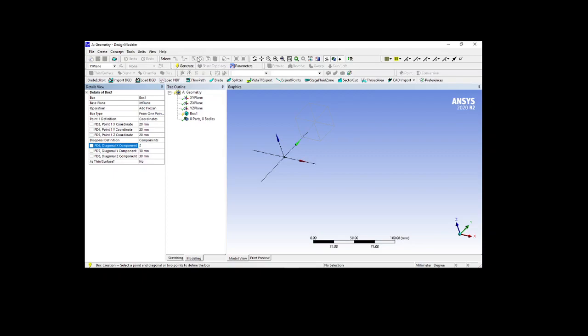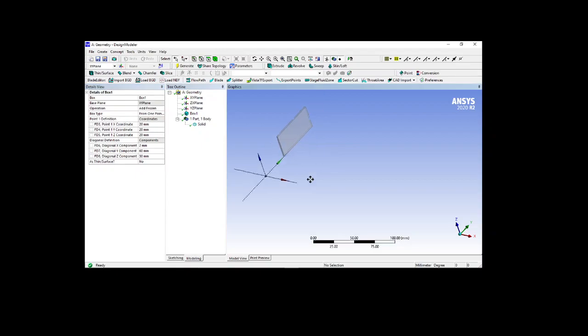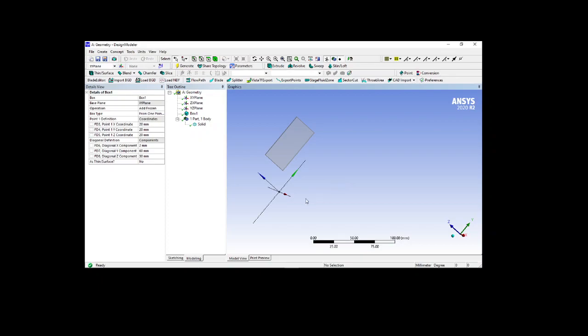Then I can generate this. Now this x coordinate becomes 2 mm and y coordinate becomes 30 mm, and I want the y coordinate as 60 mm. So I am able to create a slab here like this. Okay, this is how we are able to create the slab by using the primitive types. Okay, primitive types. This is how.